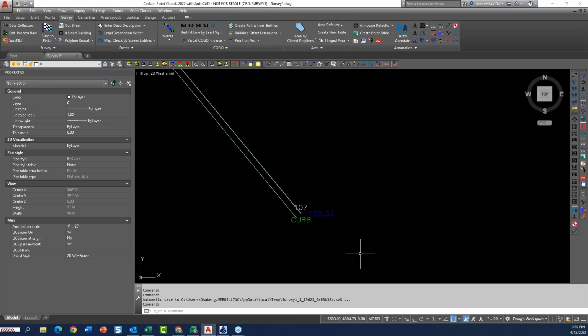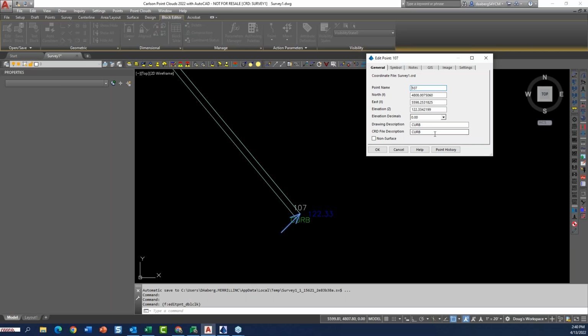Also, you can control that template. So I have that set as a default for a half a foot reveal. You can also control that template by using your vertical offset. So if this was a V.2, that means it's going to start that template with a 0.2 reveal instead of a 0.5 reveal.